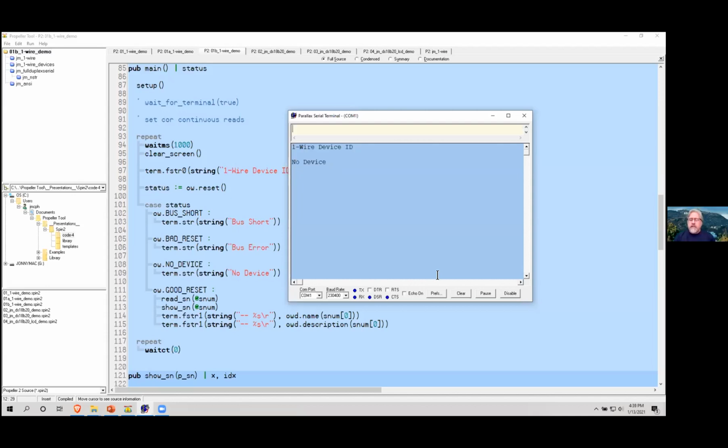Sorry, thank you for bringing that up. No, the iButtons only have 2 connections. They have signal and ground. A lot of one-wire devices do what is called parasitic power. You'll tend to see, and for the newcomers, if I say stiff pull-up, it means it's a low value resistor, so it can provide more current. So with a stiff pull-up, the device will charge itself from the bus.